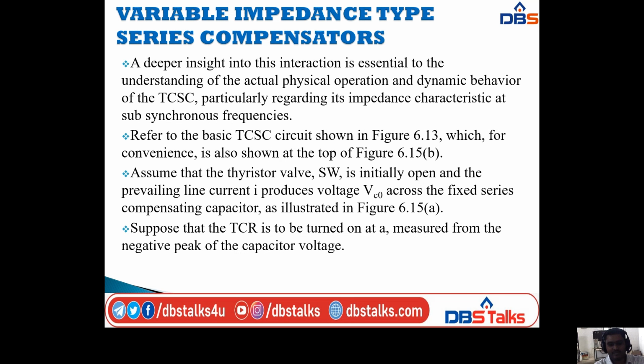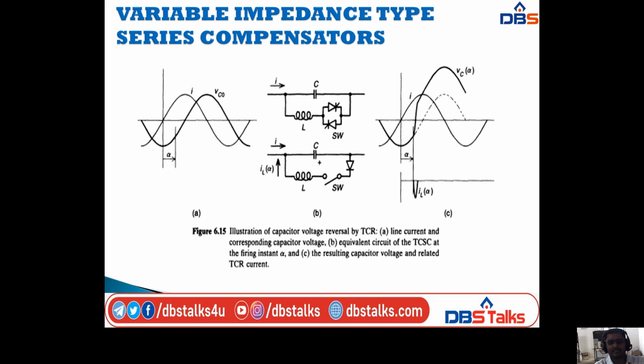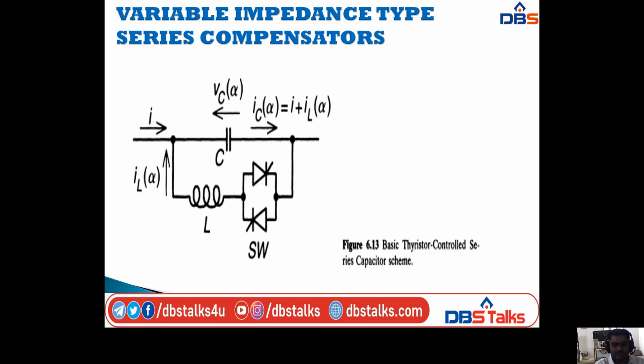Next, suppose that the TCR is to be turned on at alpha, measured from the negative peak of the capacitor voltage. The diagram is shown like this, that is the C diagram. The C diagram gives the resulting capacitor voltage and related TCR current. So this is the basic thyristor control scheme for the capacitor scheme. Already I discussed this one.